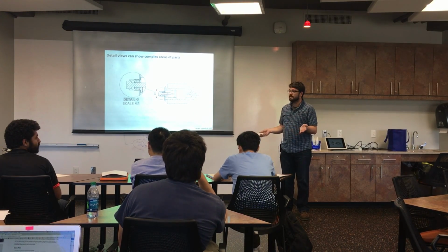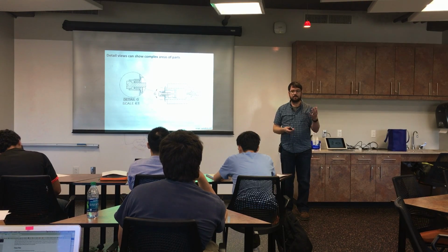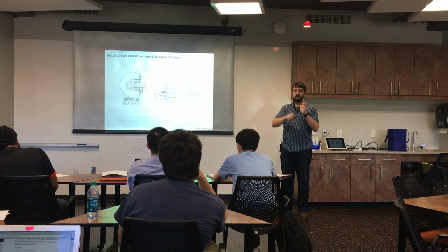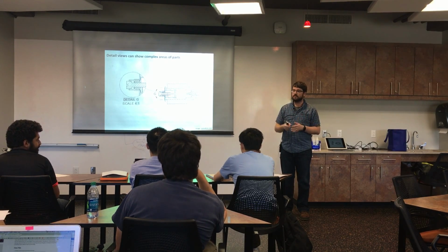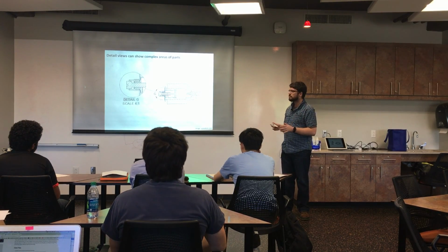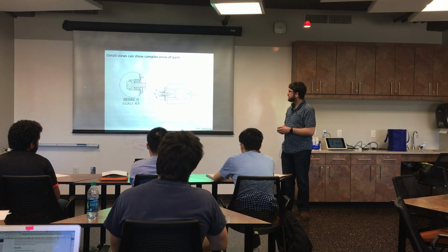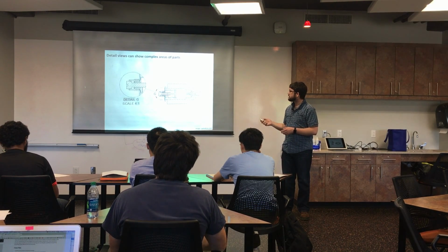So for example, a lot of you are familiar with the side blocks for the biax. We could have a drawing of the blocks. The teeth are going to be pretty small, so you could have a detail view that blows up the teeth. Probably not quite necessary, but it's nice to make life easy on your machinist.